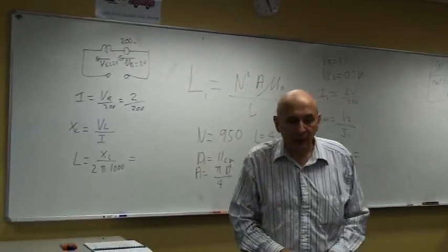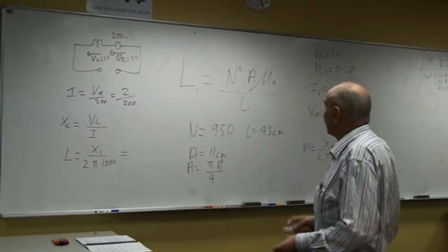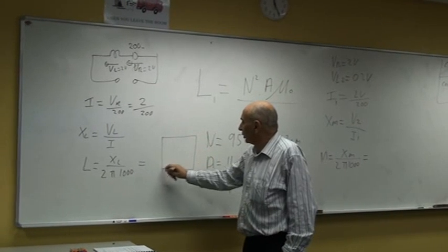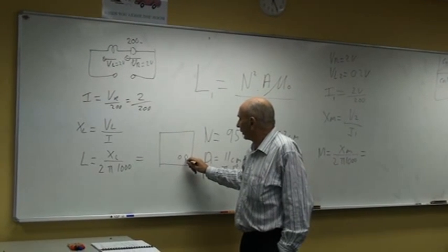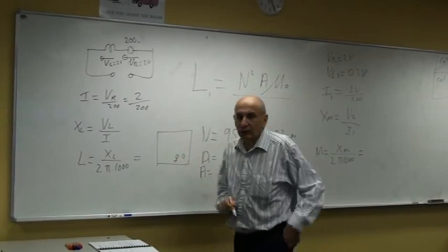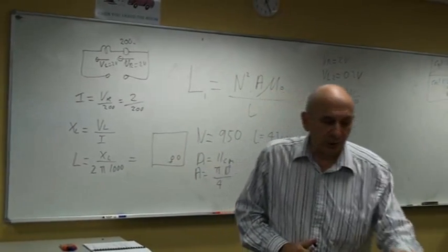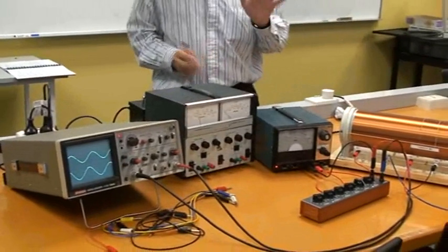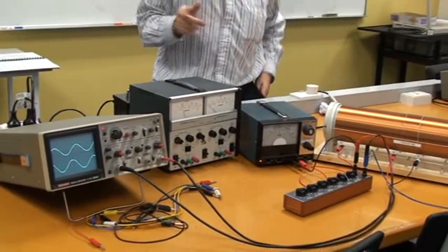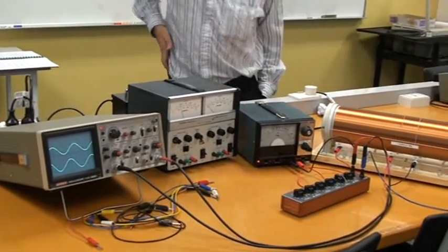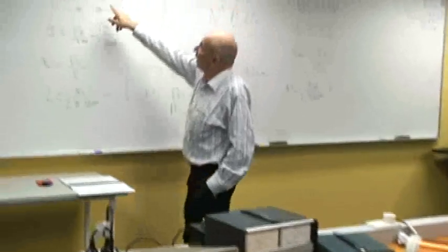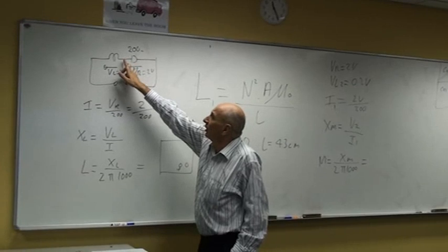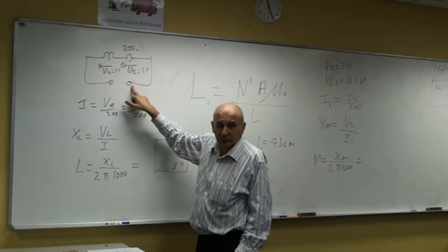And finally, the very last thing I want to point out is that I hope that some of you, when you watch this film, have remembered that on the signal generator, one of the terminals is earthed. That one is earthed. And yet, when I wired up the experiment, I didn't put the earth on the earth terminal. Now that's very unusual. That's only ever going to apply in this particular lab. The thing is, I wanted to measure both V1, VR and VL, so I had to earth this point. If I put an earth here, I cannot have an earth there as well.